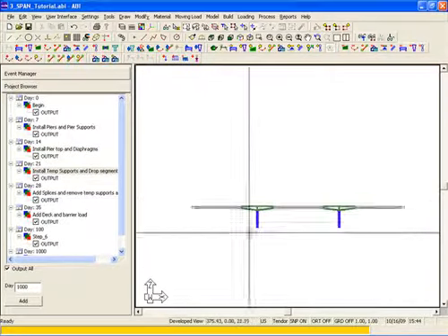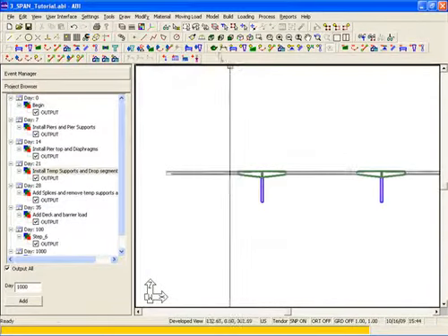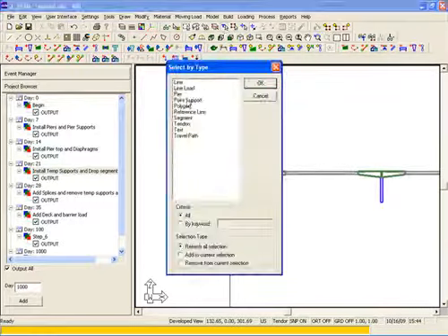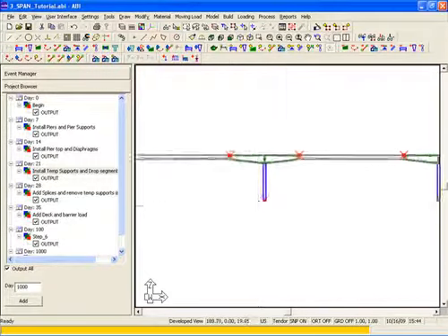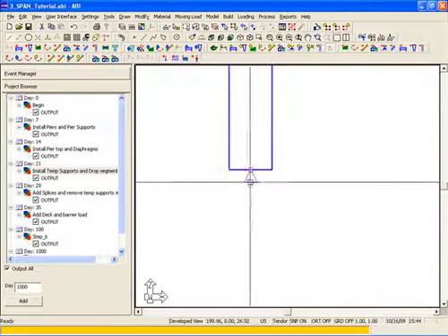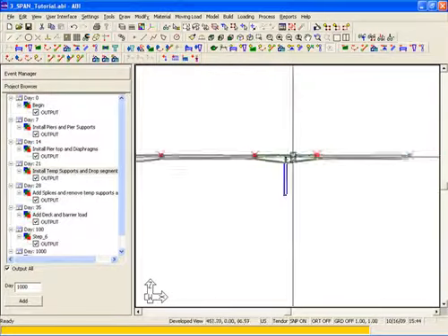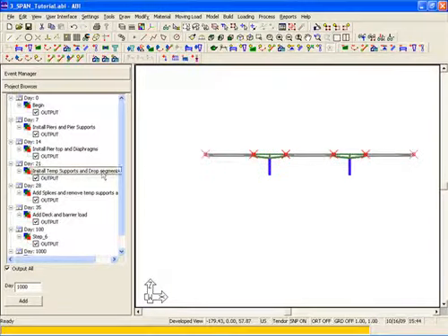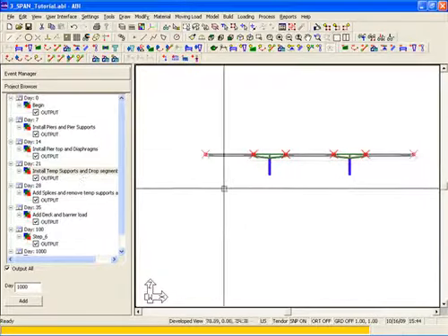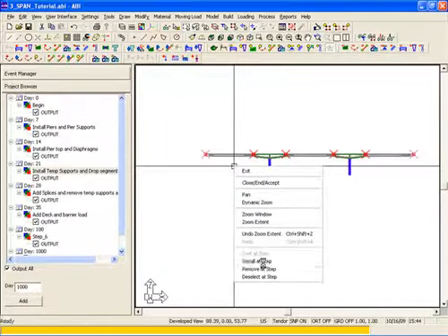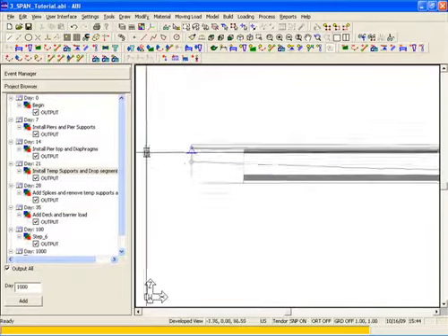The first thing we'll do is select the supports. To do this, because most of our supports are temporary supports, we're going to go to Select by Type, and we're going to select Point Support. We're going to hit Control, and we're going to turn off the supports at the base of the structure. The remainder of the supports are going to be temporary supports except for the abutments. But these supports will also be installed with the temporary supports. So we're going to right-click, say Install at Step, and now those supports have been installed. You can tell that by the color change.